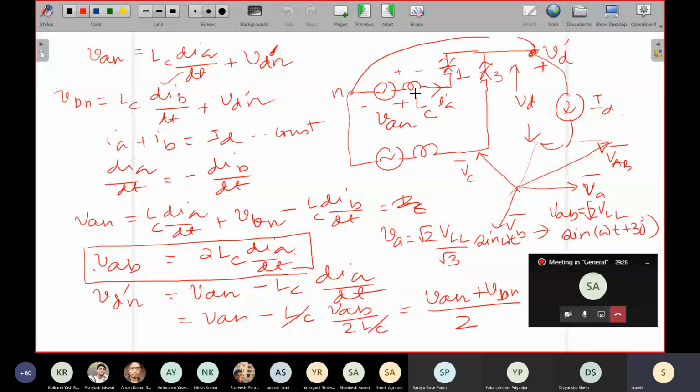Yeah, you see that in this figure, if there is instantaneous commutation, that means current changes from TH1 to TH3 instantaneously, then what happens? The point potential VD dash becomes VB, because this is minus plus VBN. Instantaneously the voltage becomes VB. We are not getting some other voltage, right? How much voltage have you got?